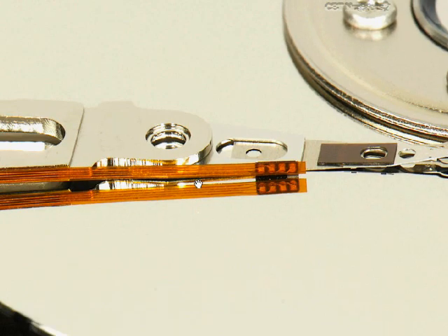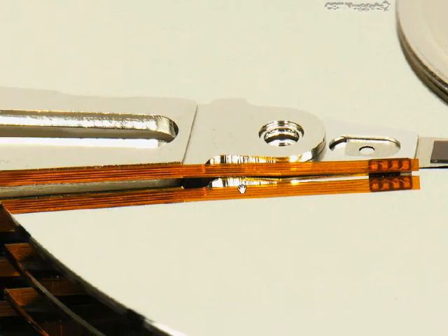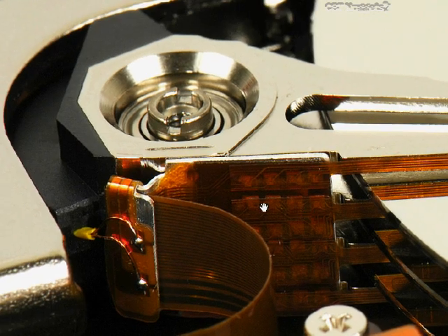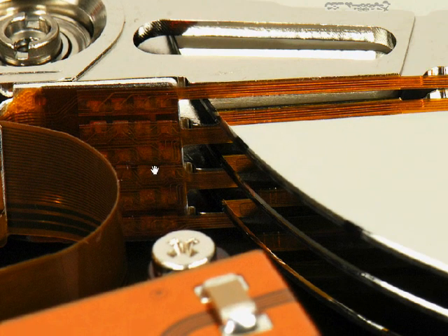Also, by the way, this arm right here is called the actuator arm, and then the mechanics that actually control the function and the movement of all of this is inside of this more centrally located position in here. And that's where it controls where to actually put those heads. Notice that there's also multiple platters, and each one of these actuators will have a head on it, and there will be one under here which will actually read both sides of this platter.